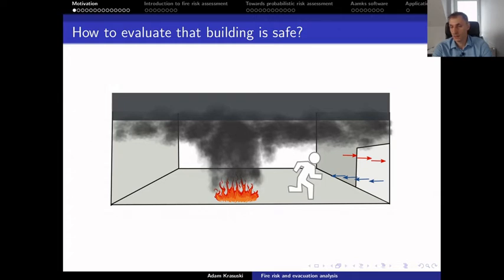During a number of years we collected knowledge which solution, which safety measure are efficient in a number of previous fires. Standards and codes also contain some level of conservatism. So, in other words, there are some safety measures added to be sure that regardless of the geometry or layout of the building, we are still on the safe side.